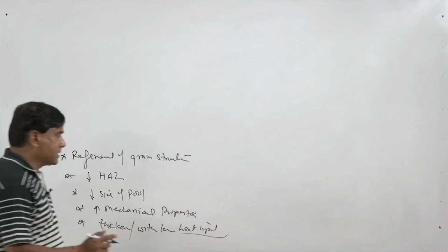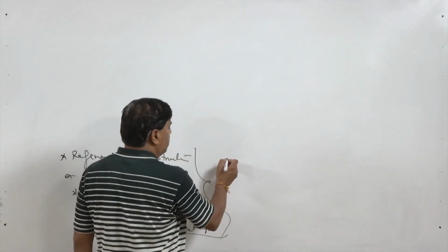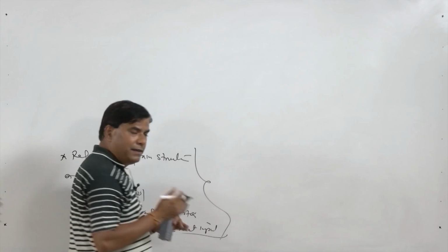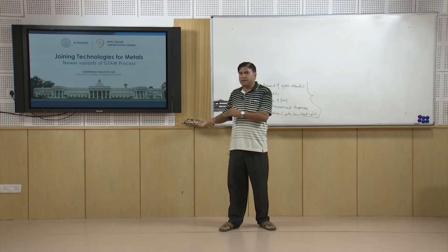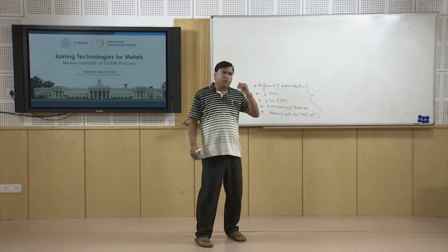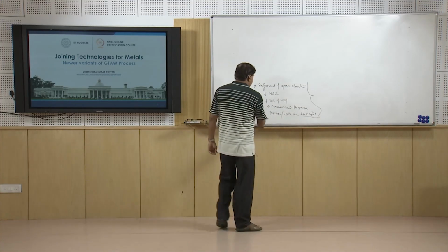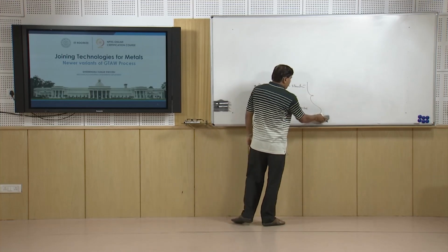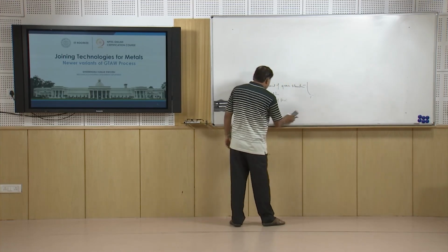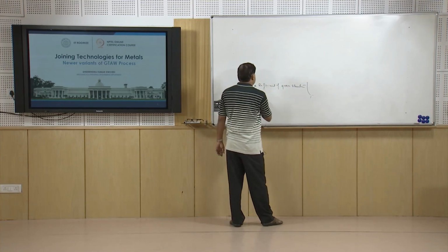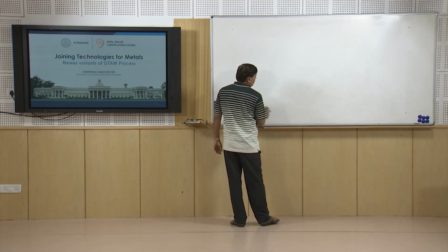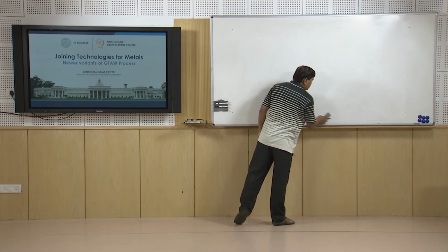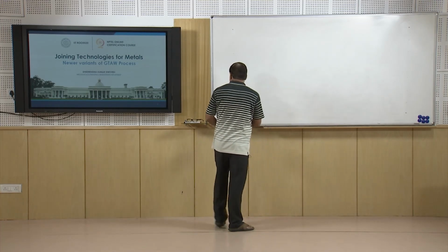So, all the metal systems which are very sensitive to the heat input are welded using the pulse GTAW process, like hardenable steels and precipitation hardenable aluminum alloys. Whatever the metal systems whose performance is adversely affected by heat delivery, especially to the heat affected zone, it is always good to weld them using the pulse GTAW process.